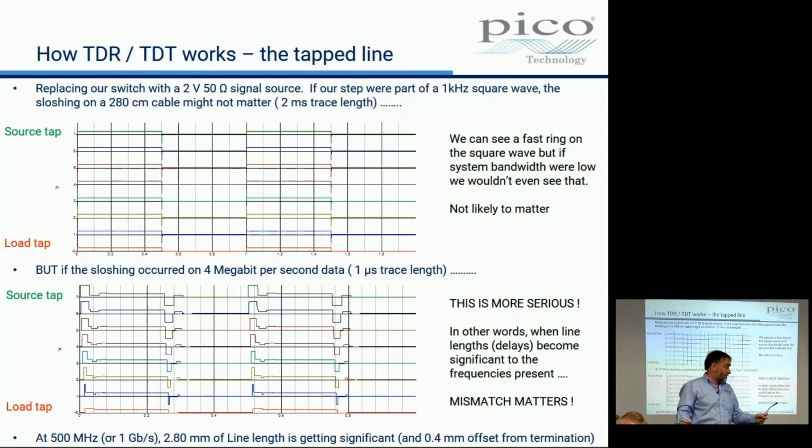So if we think about what USB 3 is, 5 gigabits per second, isn't it? If we were using a piece of cable this long, we better not have mismatch at the end of our cables, otherwise we're going to be in dead stuck. So when we design the cable and when we design what it feeds at the ends, we better know all about the match at the ends. What do we need? Well, a network analyzer. And we can use the VNA or we can use the TDR TDT approach.